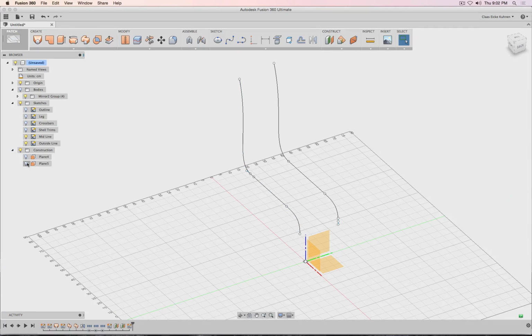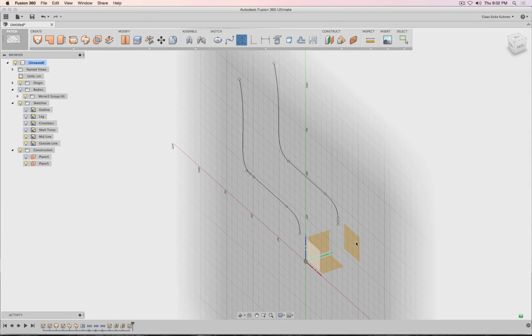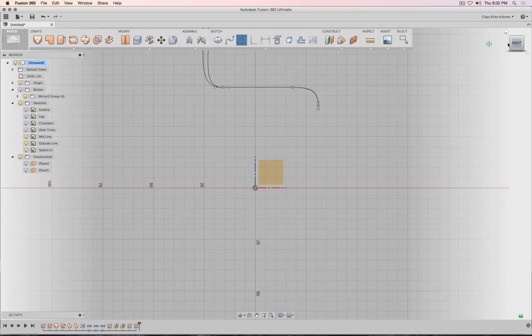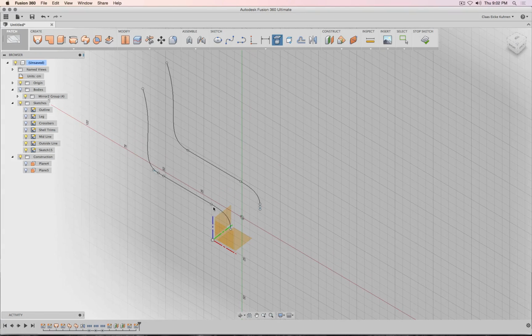and onto that other construction plane I'm creating a new sketch there, but I'm not going to draw everything. Now what I'm going to do is simply project onto this sketch the profiles from this sketch. So number 1, 2, and 3.